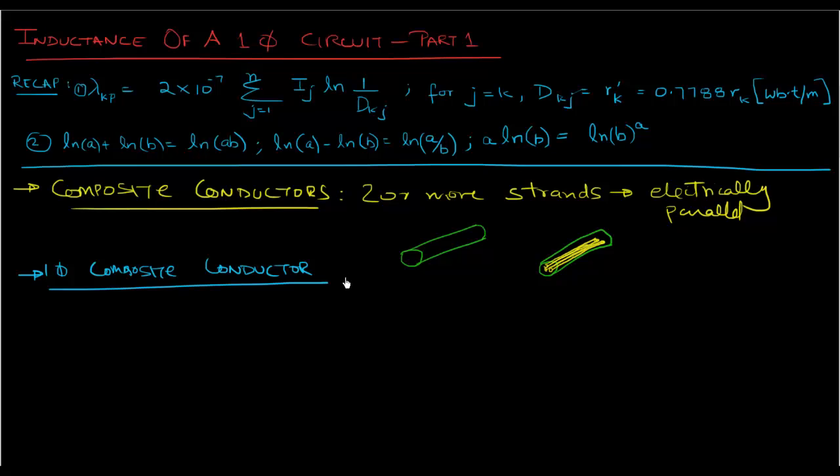You're going to use the same formulation that we derive in this video and the next, and the inductance formulation that I get, I will use that same formulation to show you what the inductance would be for a single phase conductor having just a solid conductor. So we'll do this generic equation. The only conditions we have here though: one, that these strands be cylindrical, so we have cylindrical strands. And the other condition would be that all these strands share the current equally.